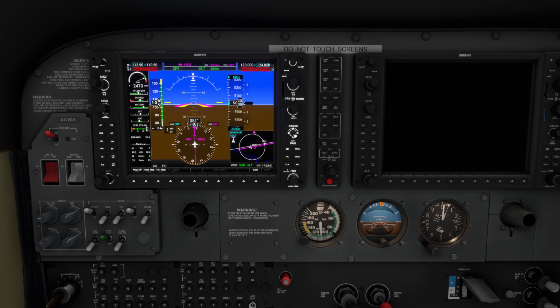And again, the range controller on a primary display is going to control the range zoom for that. We also have access to all of the GPS functions. I'll go ahead and turn the map off here by using the GPS controls over on the right-hand side here. So we can go into flight plan and we can edit our flight plan. The layout here is a little bit smaller than it is in your multifunction display, but we still have use of the flight plan. And we can go in here to procedures and we can select approaches and activate approaches